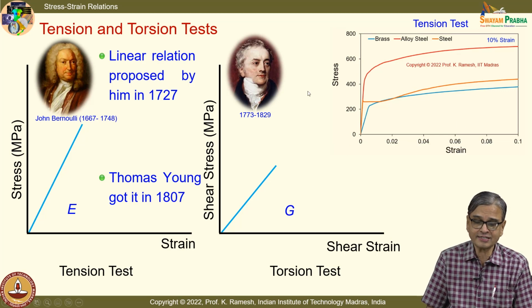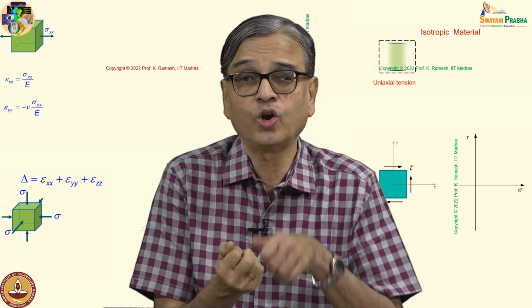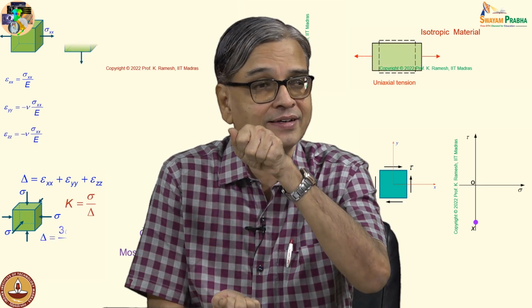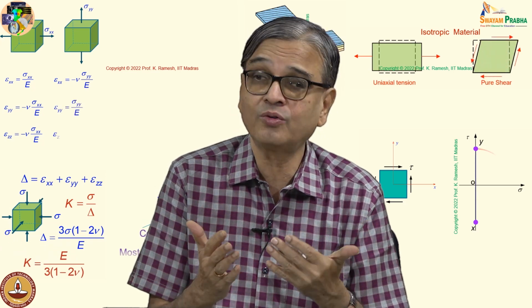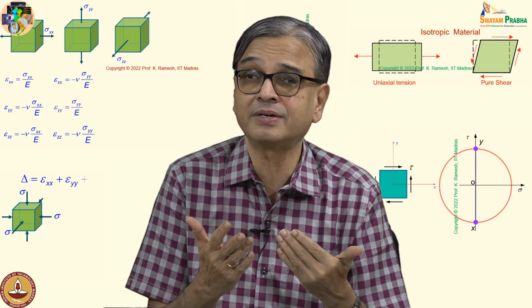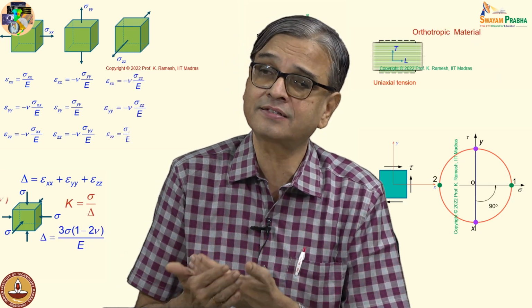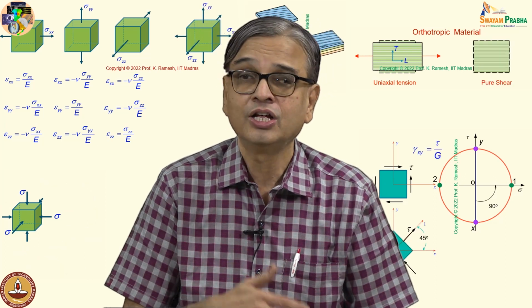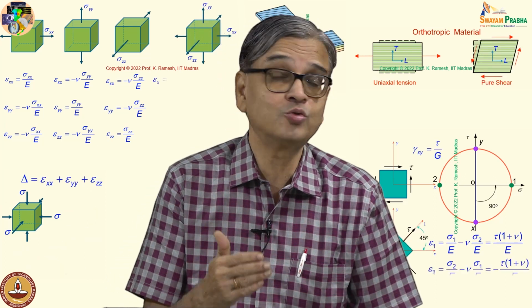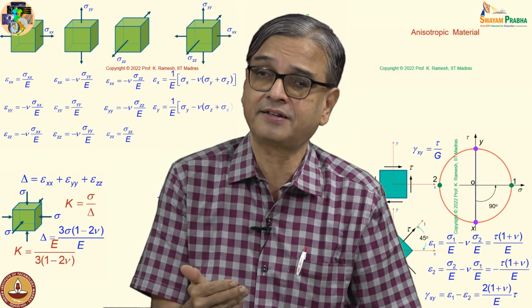And you should also understand that this is plotted for the bulk material. And how the loading is done? The loading is gradually applied, and it is done at room temperature. See, now we work on extreme environments. We work at very high temperatures as well as very low temperature, like your cryogenic engine and so on. So those applications, you have to redo the tension test and characterize the material.